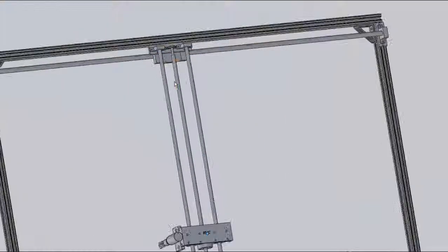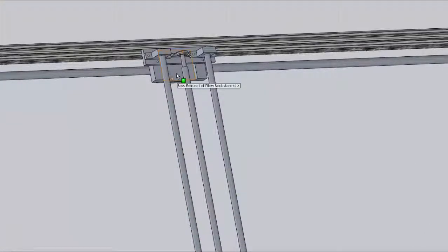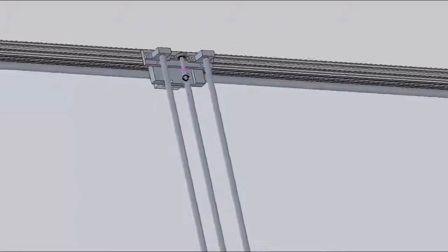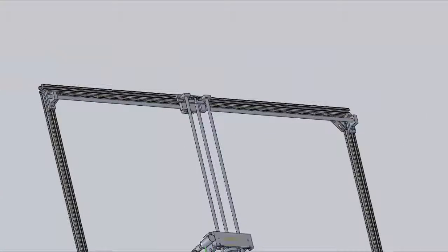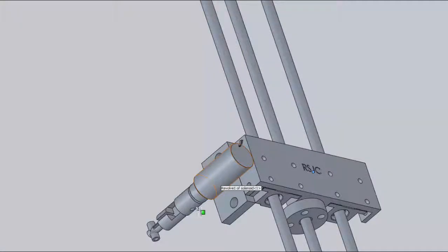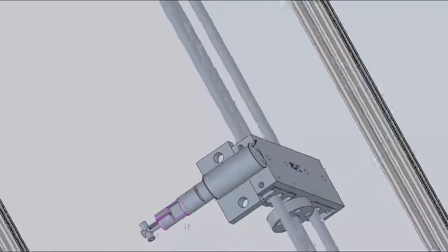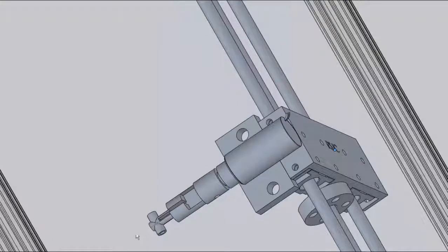On the other end we have a final 3D printed part for the supports, the large pillow block stand, where we have mounted the other end of the guide pins and the lead screw. So on the small nut connector we have a solenoid mounted and a pin solenoid connector, so that when the solenoid is engaged, the pin is pushed down through here into the surface.